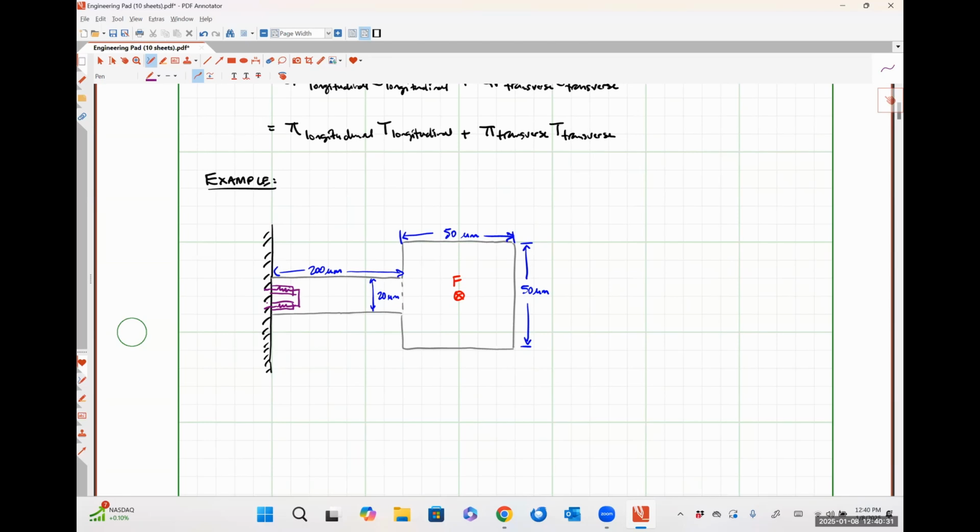At the anchor. So if we put our piezo resistor at the anchor point, it's going to see the largest amount of stress or strain and therefore generate the largest signal. If we put it further down the length of the beam, the signal that would be generated by it would be much smaller because it would see less stress and strain. So we want to put it somewhere kind of obvious, wherever the maximum stress point is.